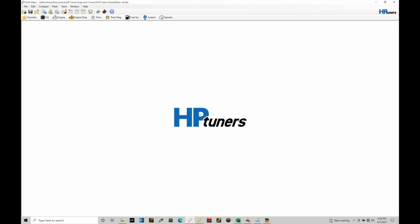So first things first, I have my 2018 Yukon Denali calibration file. This is an L86 engine. This is a naturally aspirated engine, and I plan on going forced induction with this and adding on a Magnuson supercharger kit. So I'm going to have to prepare my zones so that I'm able to have better fueling and better characterization as I get into boost, as my P ratio goes above 1.0. The P ratio is what we find in our virtual volumetric efficiency table. So let's talk about this real quick here.